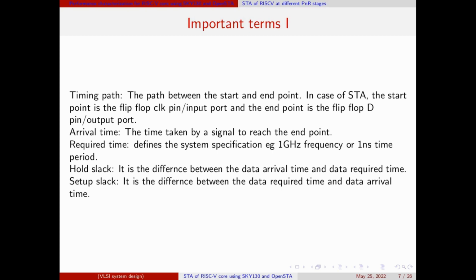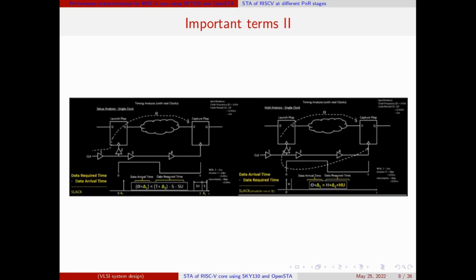Now, however, let us see what is the difference between the hold slack analysis and the setup slack analysis, due to which we got the definitions for the setup slack and the hold slack. In case of hold analysis, what happens? The zeroth edge of the clock goes both to the launch flop and the capture flop, and therefore we want the data arrival time to be greater than the data required time.